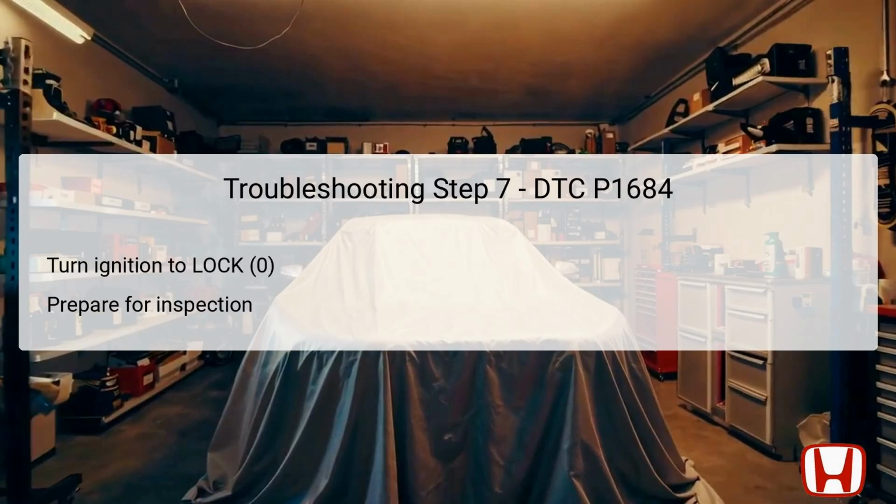Step 7 instructs the technician to turn the ignition switch to the lock 0 position. This action is essential for ensuring safety while proceeding with further inspections. The technician must take precautionary measures before diagnosing and inspecting the throttle body directly, as this can be dangerous due to the possibility of electronically controlled systems being active.